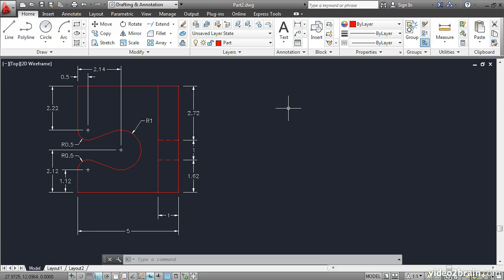Here we will explore the many ways you can use Object Snap with the project of drawing a mechanical part. Object Snap allows you to connect objects to the geometric features of other objects, irrespective of coordinate systems or regular spatial increments. Object Snap is one of the most important concepts in AutoCAD that, once mastered, allows you to draw with precision. Go ahead and open the Part 2 project file, and then click the Line tool on the Draw panel.